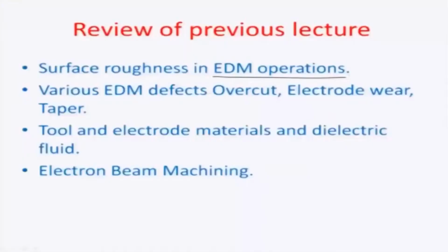Quick recap of what we did in the last lecture. We talked about surface roughness of EDM operations, electro discharge machining operations. We also talked about the various EDM defects like overcut, electrode wear and taper due to the unequal exposure of the workpiece to the sparks coming from the tool electrode. We also talked about tool and electrode material and dielectric fluid,